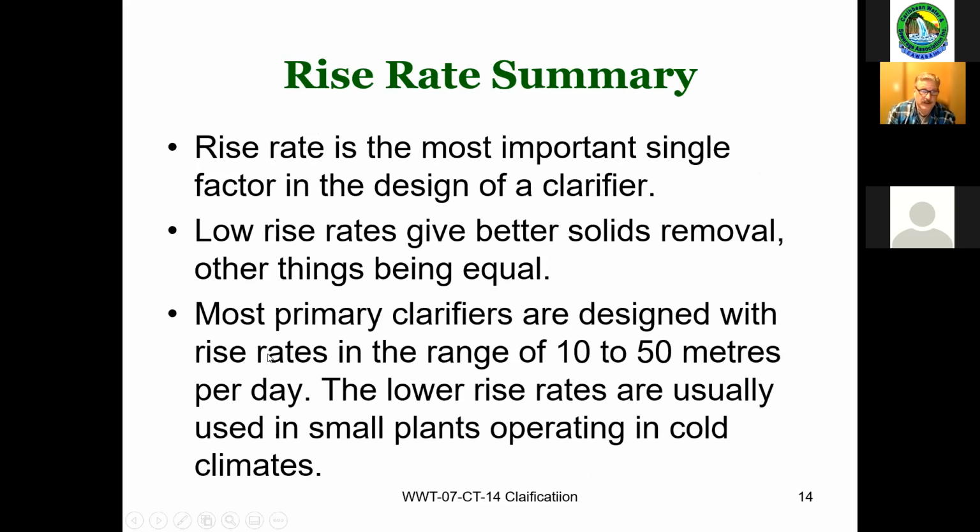So in clarifier design, rise rate is one of the most important factors. Low rates give better solids removal, for sure. Most clarifiers are designed within a rise rate range of anywhere from 10 to 50 meters per day. The low rise rates are usually used in small plants operating in colder climates.